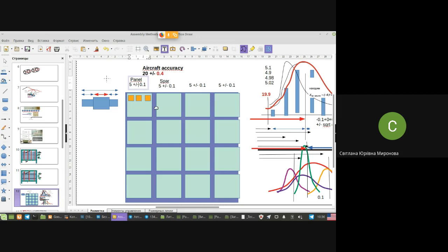That is too simple an example. Actually, it's, let's say, too direct, too literal. It's not completely correct when it comes to assembly in jigs. Not completely correct, but the idea is rather similar. In order to assemble something with the demanded accuracy, the components of the assembly unit, the components of the aggregate, should be a bit more accurate, normally, if you use the same assembly method for both of them.